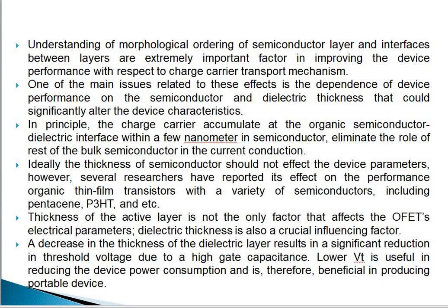Thickness of the active layer is not the only factor that affects the organic field effect transistor electrical parameter. Dielectric thickness is also a crucial influencing factor. Next, a decrease in the thickness of the dielectric layer results in a significant reduction in threshold voltage due to a high gate capacitance. Lower threshold voltage is useful in reducing the device power consumption and is therefore beneficial in producing portable device. If you are reducing the threshold voltage, you can scale the device further. This will be beneficial in very large scale integration circuit designing.